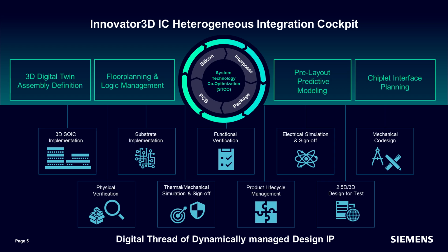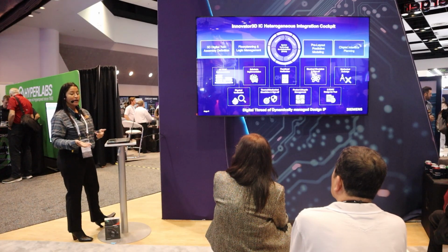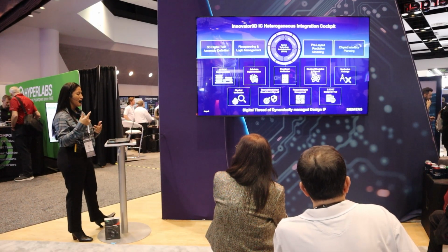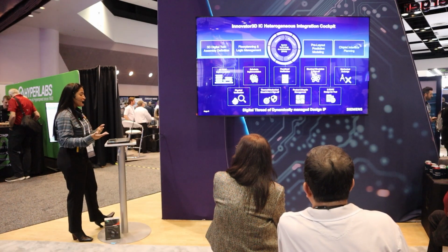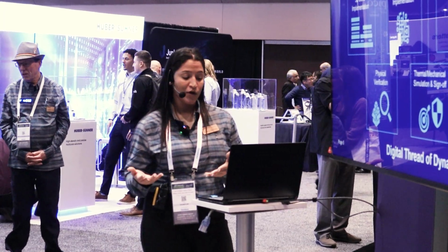So one of the challenges with these types of systems, let's say we're dealing with an SoC or a couple SoCs with some HBM on a silicon interposer that's sitting on an organic substrate, is how do you manage that logic? How do you author that logic in a typical system? You may have a schematic or an RTL netlist, and all of those may be input options for an HI system, but what environment is the keeper of that logic?